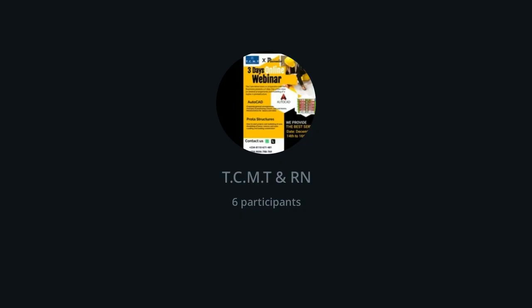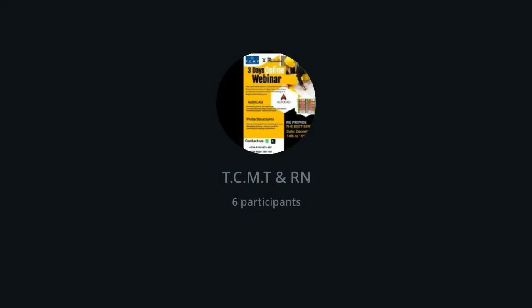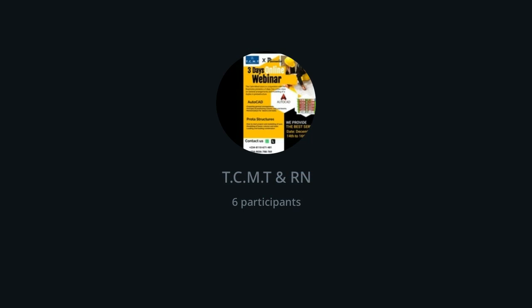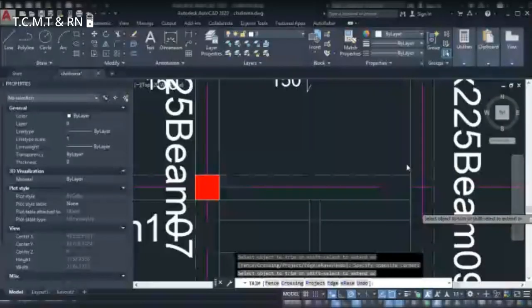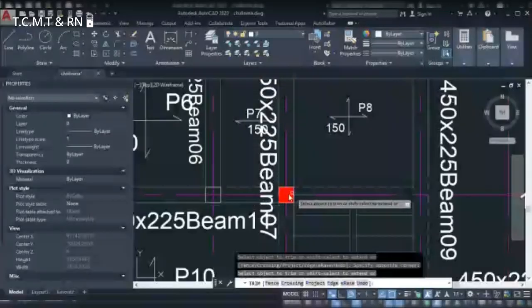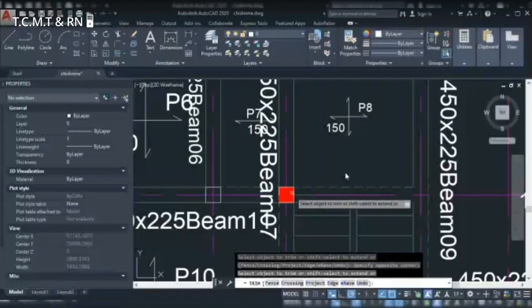So this one, the girder beam, that is the beam that's carrying the staircase, is secondary at this end. This is supported by a column here and then supported by the beam at the other end.